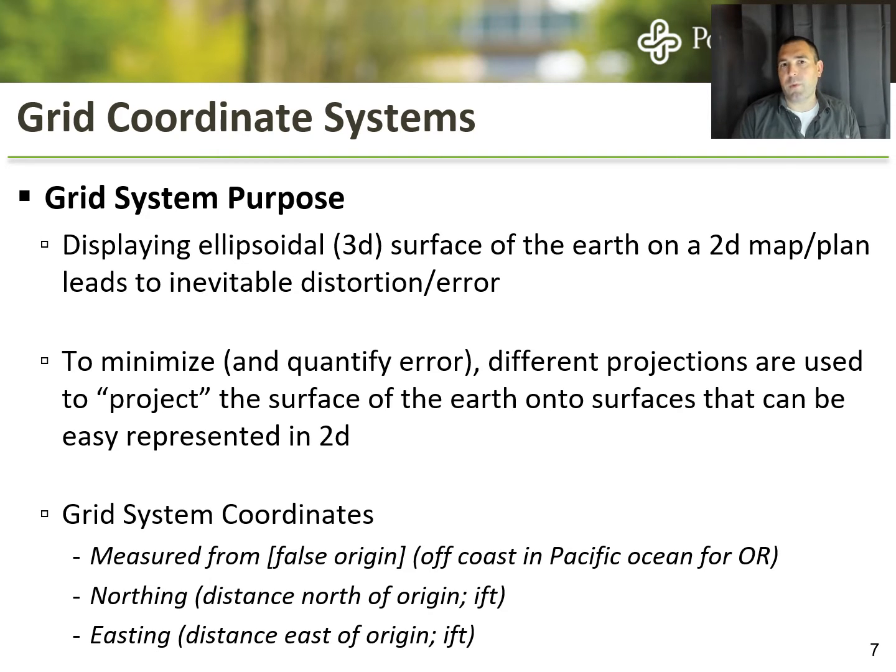And so the way that we approximate it takes one of two main forms that we'll talk about in a second. But generally speaking, it involves taking the curved Earth, putting something on top of it that we can then project points out to. What we're putting on top of it might still be a three-dimensional shape, but one that can then be unfolded into two dimensions. So the two shapes that we're going to talk about would be a cone and a cylinder. Both of those, if you cut a slit in it, would then become a two-dimensional flat representation.